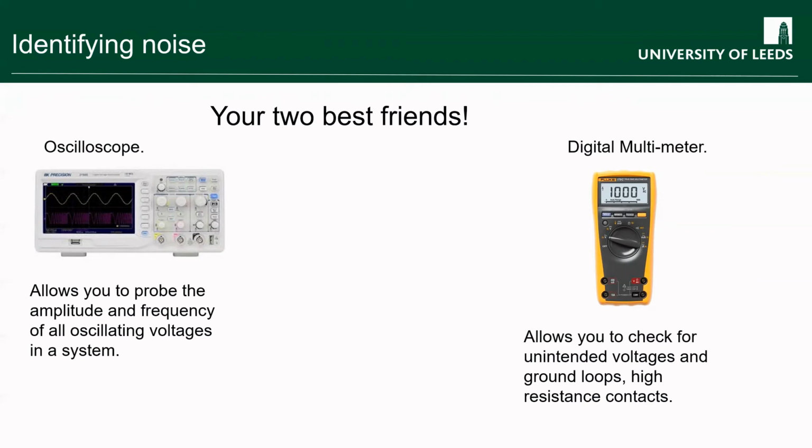about it. We were able to program the temperature controller so it would turn off the reversal for the short period of time that we were going to do the electrical measurement, and then we would turn it back on again so that we could do the temperature measurements reliably. And so we were able to bypass or defeat the noise source like that. But we were only able to see that because we were able to put it into an oscilloscope and look at the frequencies available.